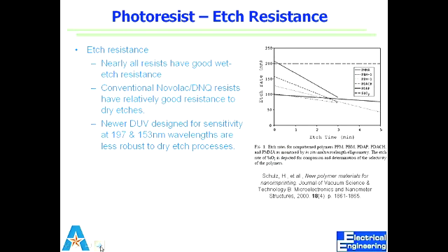Yeah. So you have this top layer which is getting etched away, but you have the products coming out as well, which would cause self-passivation of that material itself. The products are resulting in that self-passivating layer. So you'll see that word, if you haven't seen it, the self-limiting etch or self-limiting processes, where the products become resistant to further processing, which we can use to our advantage.